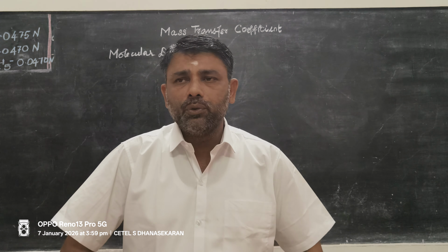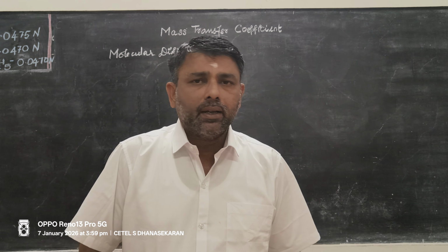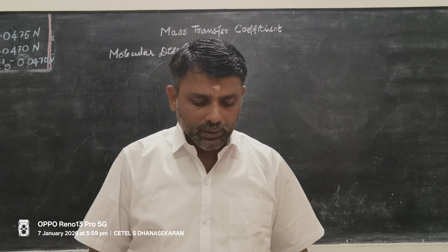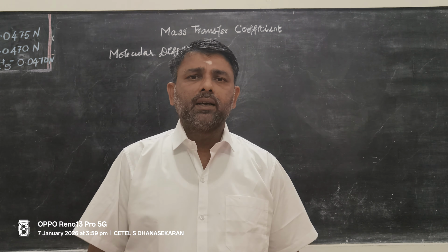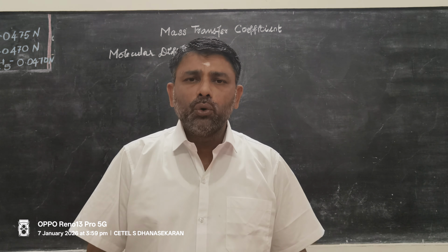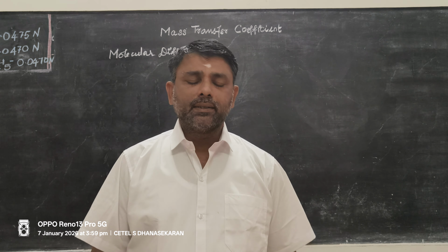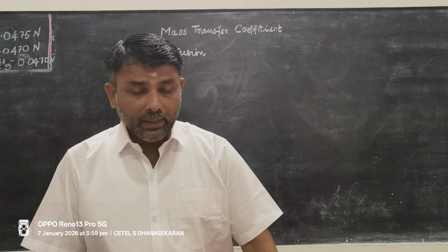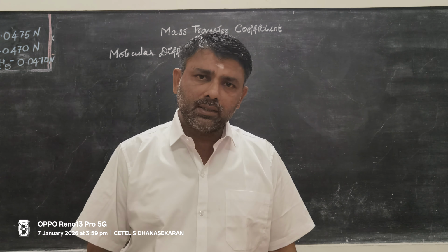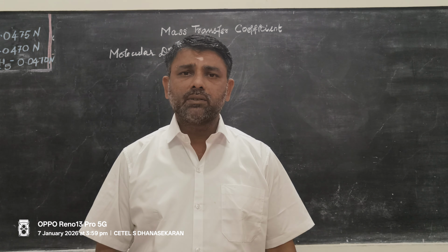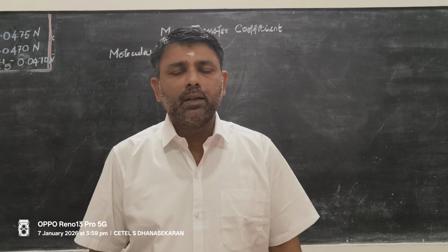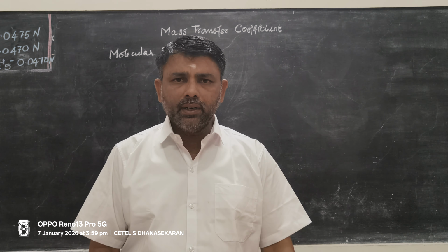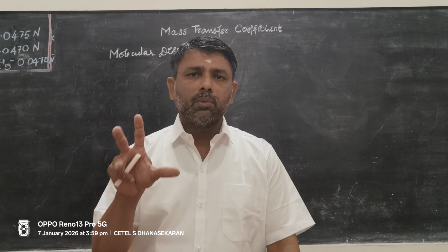One more piece of information is eddy diffusion. Eddy diffusion, I already told you, mechanical agitation causes rapid movement of fluids. This rapid movement of fluids creates large masses of fluid chunks, what you call eddies. Eddies are nothing but the characteristic nature of turbulent motion. Each eddy carries dissolved salts within it. This method of mass transfer is called eddy diffusion or turbulent diffusion. Turbulent diffusion or eddy diffusion is the mechanism of mass transfer in fluids under fully developed turbulent condition.